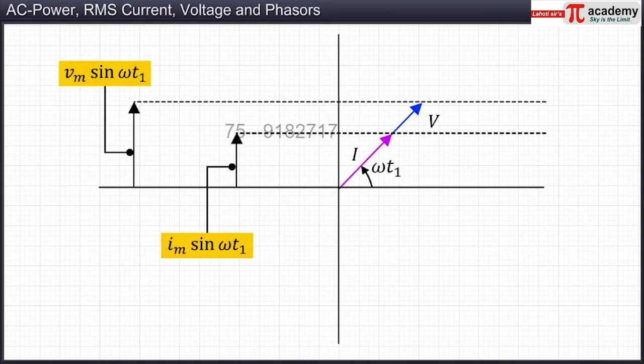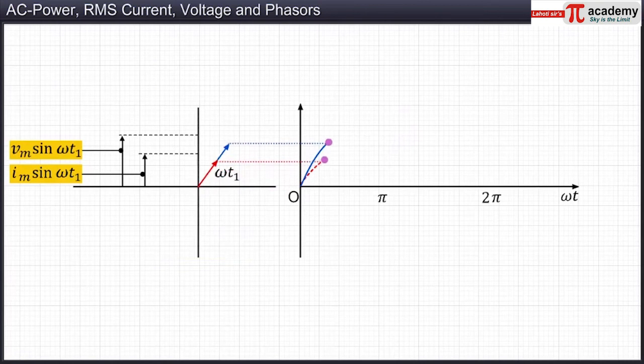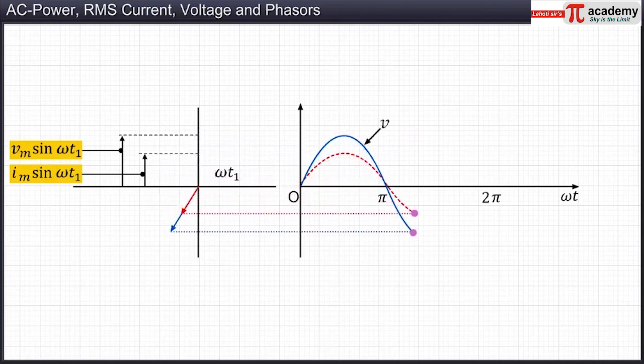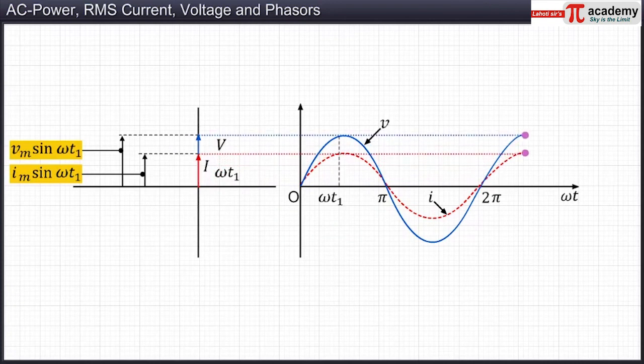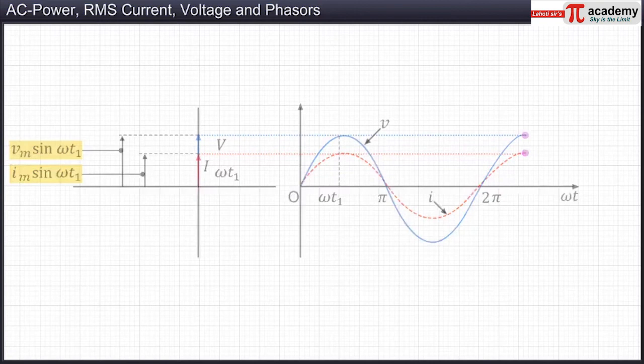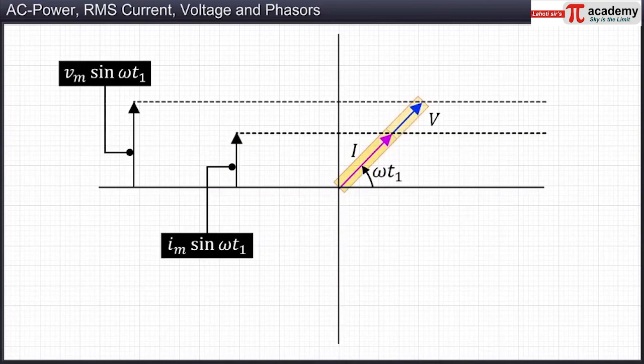respectively. The magnitude of phasors, V and I, signifies the maximum or peak amplitudes of the quantities specified by the phasor. However, the instantaneous projections of these phasors give the instantaneous values of the quantities that they represent. The phasors for V and I, in the case of a resistor, are always in the same direction. This means they are in phase, or the phase angle between them is 0.